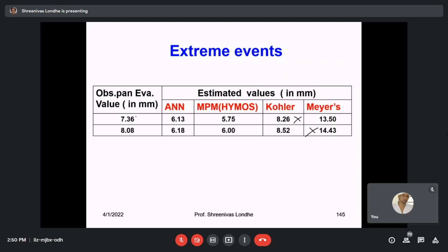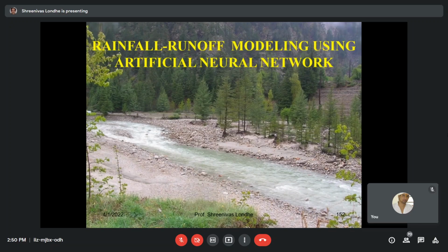Okay. So I will discuss now the last in my kitty, that is rainfall to runoff, because I have discussed with you only streamflow. But many people want rainfall to runoff, because this is a very, very practical case. The catchment receives the rainfall, and then maybe on the second or third day, a hydrograph at the outlet shows a peak. The rainfall has completely converted into runoff. Until date, there is no 100% deterministic model for converting rainfall to runoff.